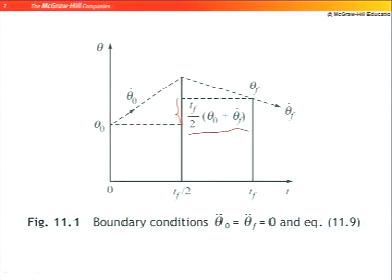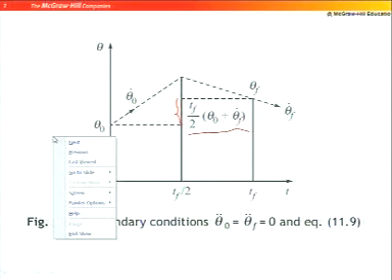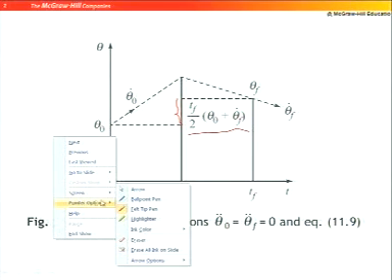Which means if the difference between the velocities, the difference between the positions, is equal to this one, then we can have a fourth order polynomial. So, in addition to those 6 conditions, if we add this following condition, we can have a fourth order polynomial to decide a trajectory.